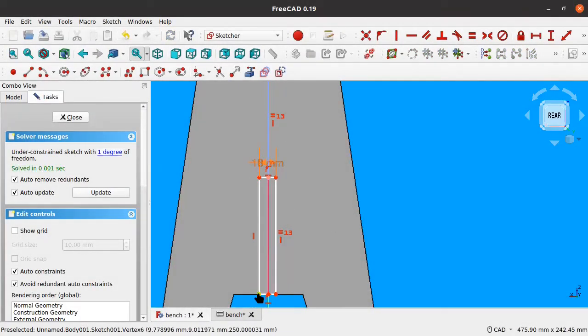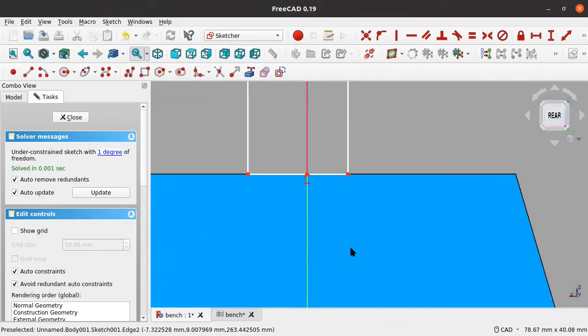And now you're going to notice that it's still not aligned to the center line. And for that, there's another magic constraint that you can use. The sequence of how you select points is important. It's going to be the symmetry constraint that we're going to be using. The symmetry constraint makes 2 points symmetrical around 1 single point.